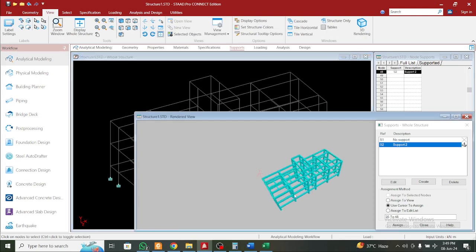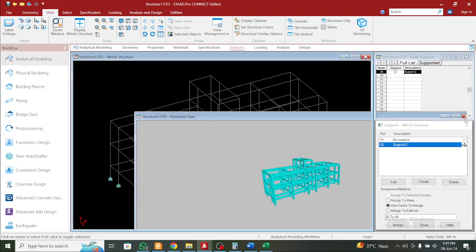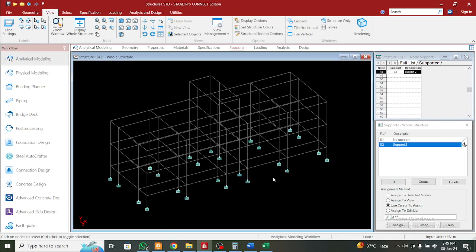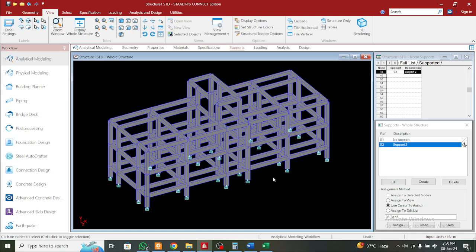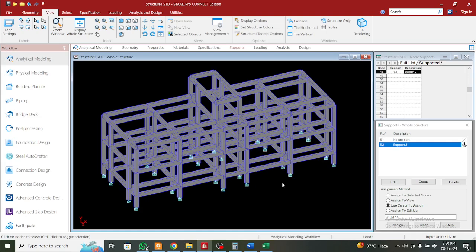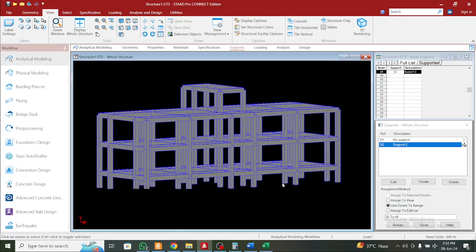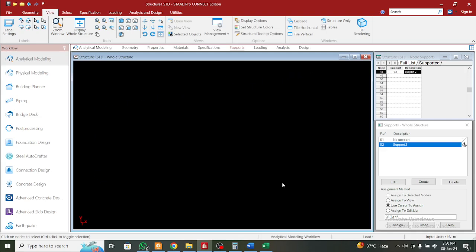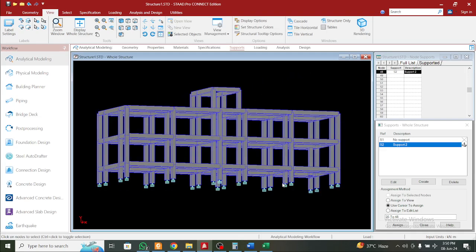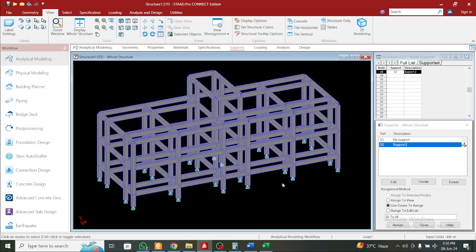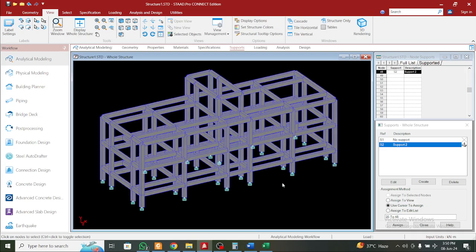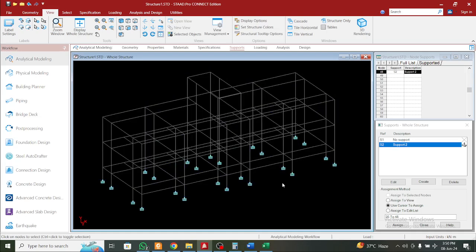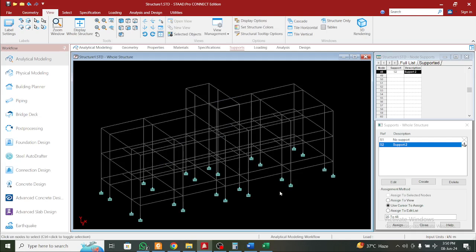This is the rendering view, and again if you press Ctrl+3, you will find this view in which you will see the frame structure in STAAD.Pro itself. So you can observe the frame. It's complete up to the mumty level. You can see we have not assigned the slabs here, because we'll put the load of the slabs in here. So press Ctrl+0 to go back to the normal view. Now the modeling of the structure is completed.